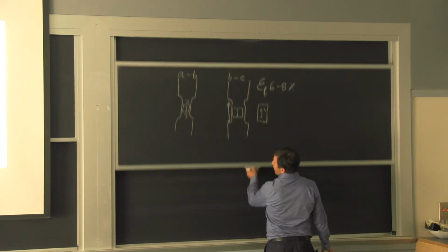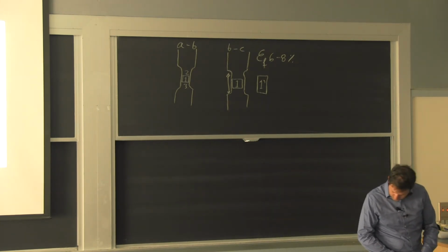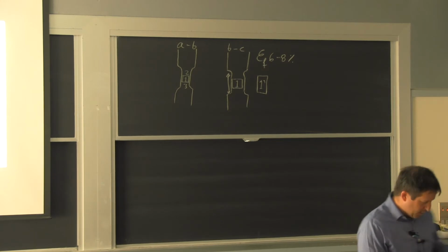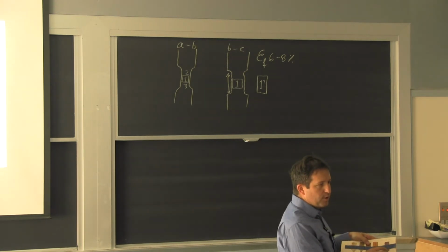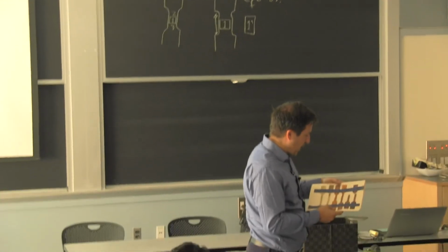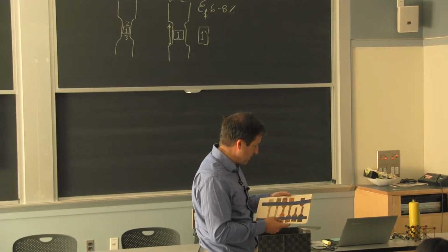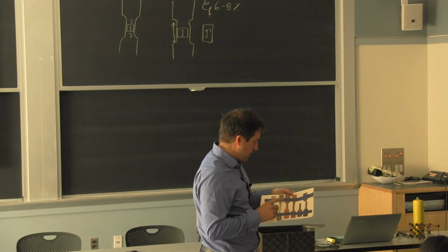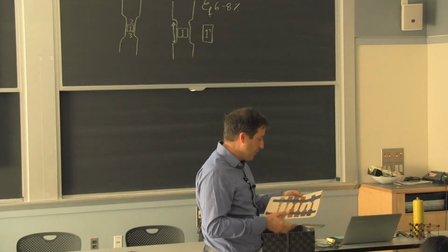All right. Now, let's move to something a little more interesting. I'm going to distribute these. So on the right side, you have 3 pieces of copper. It was the same alloy to begin with. And what happens is they were heated at these temperatures, 450, 600, and 700, for the same period of time. So you start from one material, you heat it to recrystallize it, to soften it.